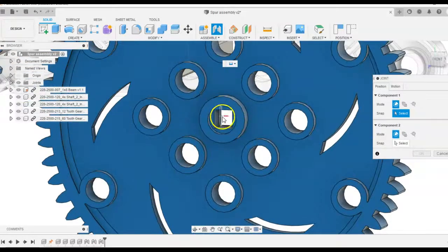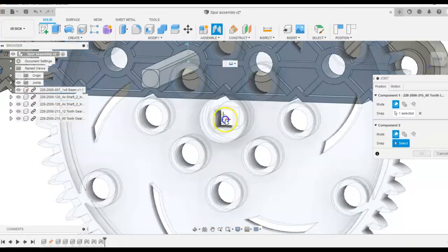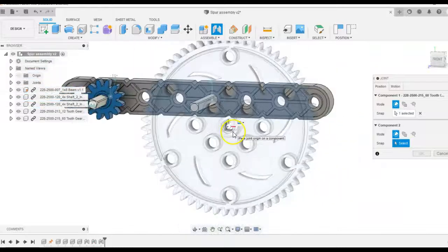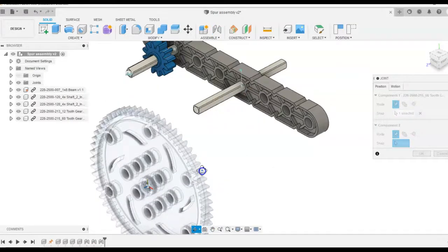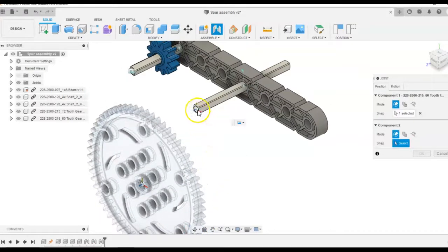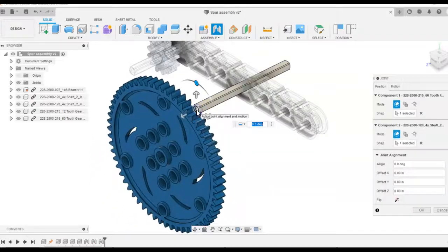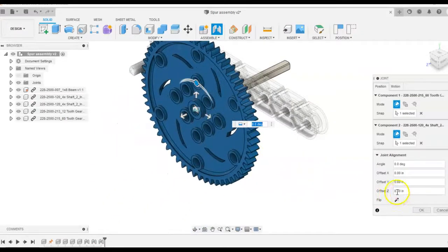Yes, and you can kind of see that circle pop up as you go by, but you can't actually click on it. It shows up when your mouse is away from it. So the way to do that is Control on your keyboard, get this all highlighted, Control and hold it. It's on the bottom left of your keyboard. And click the center. Same as before. And now I don't see the shaft at all. I know it's over there. It's like right there. I could click this, but just so I don't make a mistake, I'm going to orbit and then escape once so I may see and get to the end. Okay. And it should be the same.